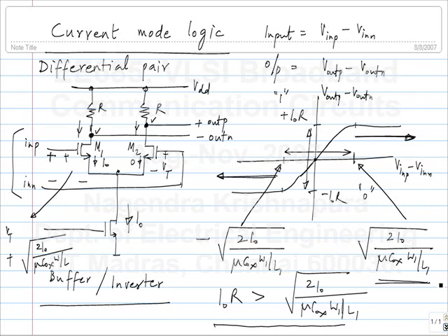I can satisfy this inequality by several means. I can increase W1 and L1 a lot, W1 by L1 a lot. I can decrease the value of I0 perhaps. Actually, decreasing the value of I0 won't help. I can increase the value of W1 and W1 by L1. Let's say they are in saturation. How is the saturation related to this? But if I keep on increasing W1 by L1, will it go out of saturation? Actually, there is a constraint and a higher constraint also.